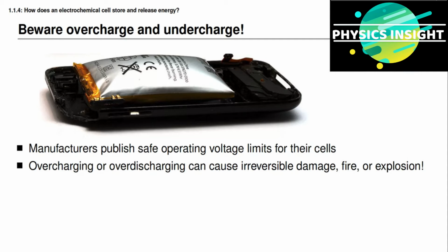And so there's this kind of a process happening at the top level of state of charge that, if the battery cell is sealed and these gases do not escape, can actually happen quite safely, and it doesn't cause degradation of the battery cell. This process at the top of charge is called a float charge, and many lead-acid battery chargers are designed to have a float charge to maintain the battery at a top state of charge.